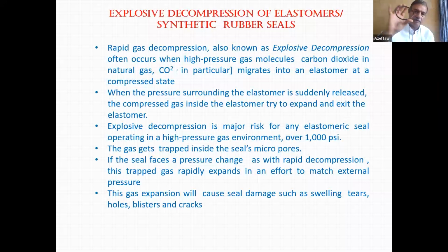So this rubber element, which is your barrier actually, regardless of whether it is this one, the BOP, or the RAM, has gases inside it. When the temperature rises, these gases start to expand.